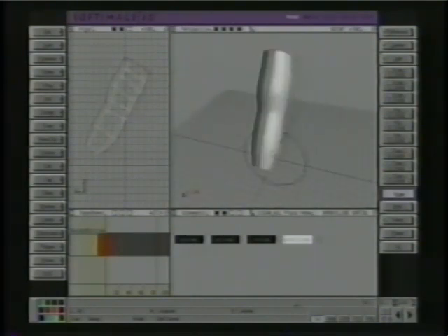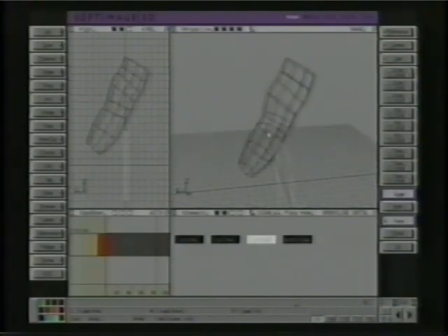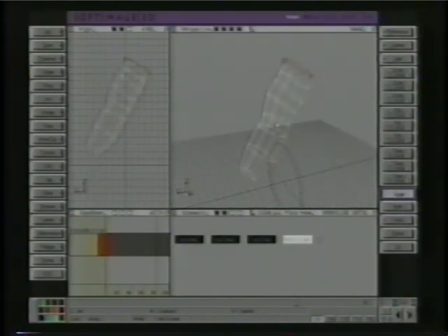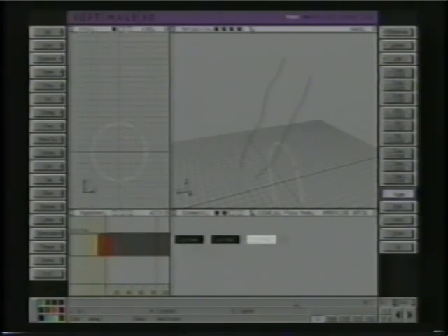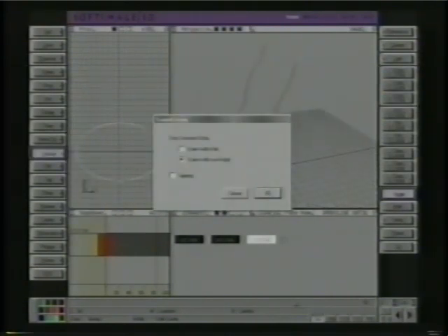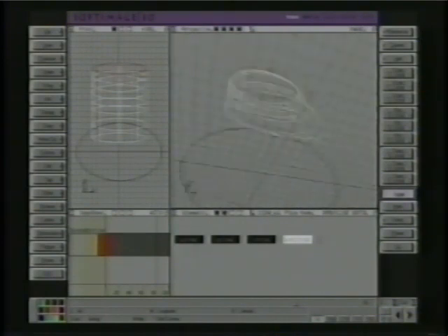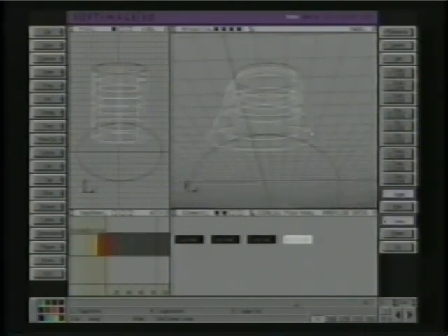So what this does is creates this new surface here, which is based on this curve and those two other curves. So what happens if we now want to change this curve, for instance? I'll go into this other window. If we want to scale it, Surface, Guided Extrude. This time, instead of Scale Width and Height, we can choose Scale Width only. Select those three again. And this time, it's really wide, just like the circle was.